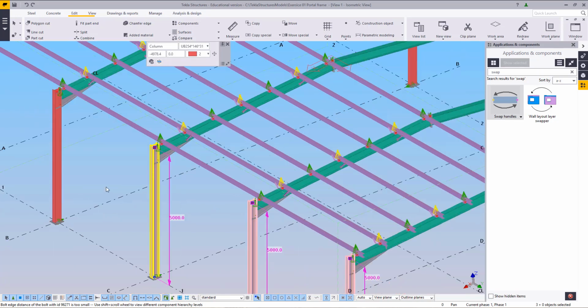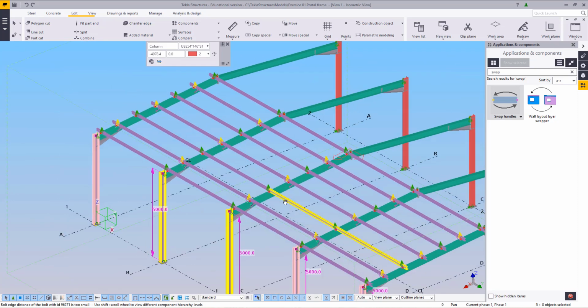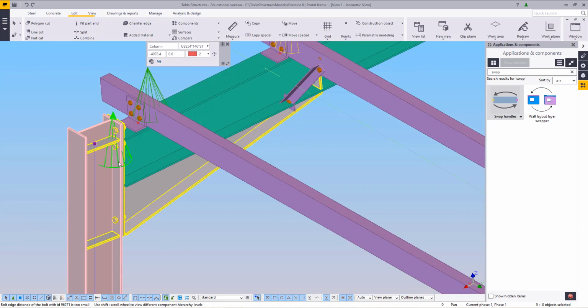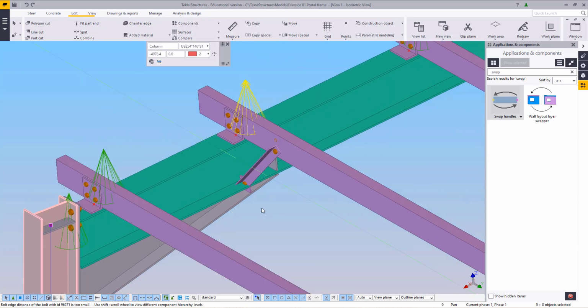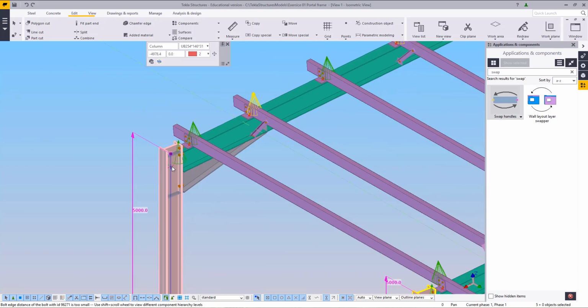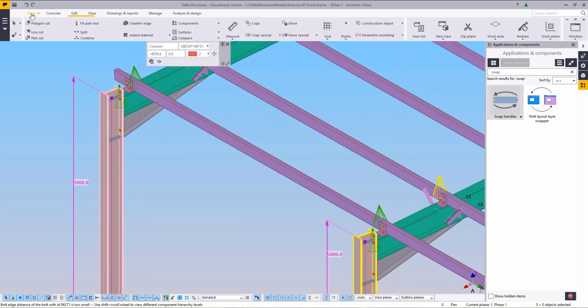Now, firstly, what I'm going to do is put in my eaves members. The eaves members are basically a beam, a pipe, anything in that order. That's something that I'll have to fix. That comes in right here at the top of the column, bottom of the rafter, between the two items.